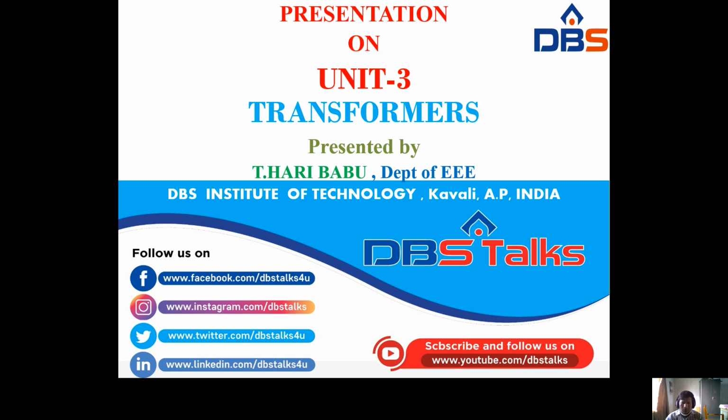Good afternoon, students. In the last class we discussed the equivalent circuit of a single phase transformer. That is, we have to determine the shunt branch parameters R0, X0, and also the series branch parameters R01, X01, as well as R02, X02, depending upon whether we use the equivalent parameters referred to the primary or referred to the secondary.